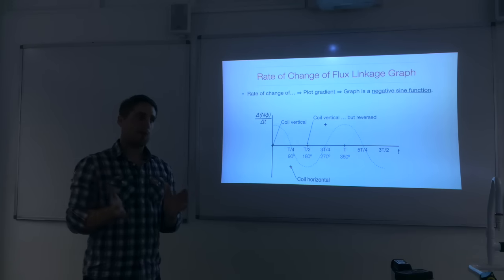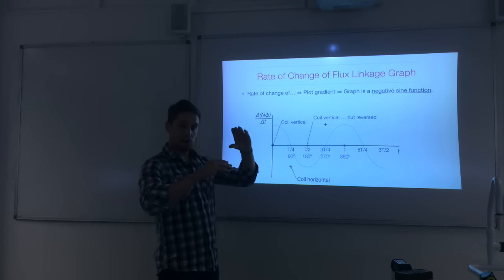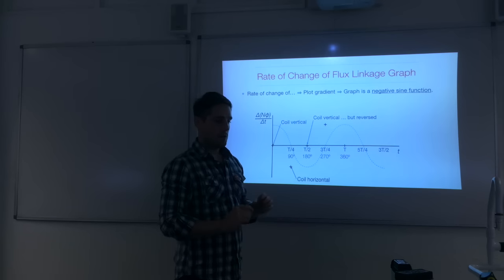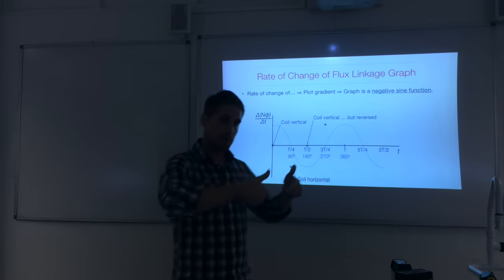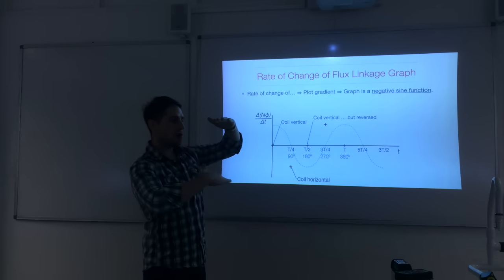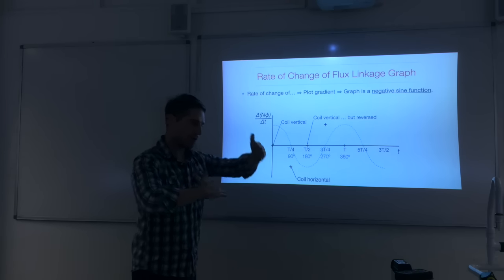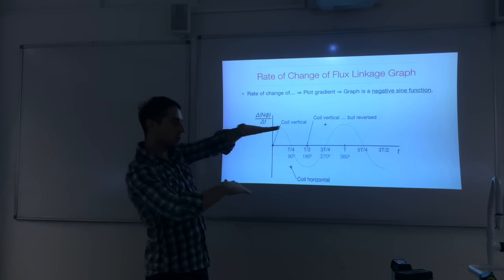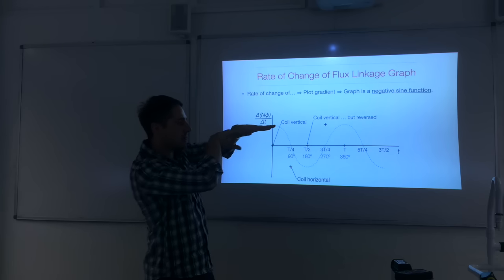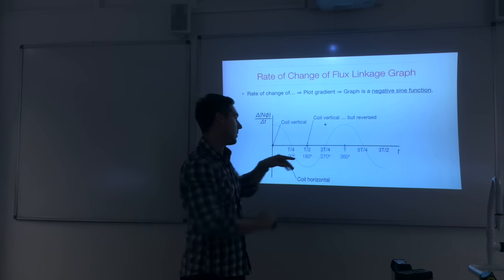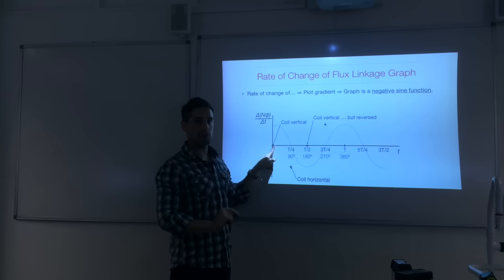Okay. The other thing you can think about here is if you think of this as a rectangular coil rotating in a magnetic field, the top and bottom edges of the coil are what are cutting through field lines, right? So when the coil is vertical, the field lines are horizontal, and that top part of the coil is also moving horizontally, so it's moving parallel to the field lines there. 0 rate of change of flux linkage.